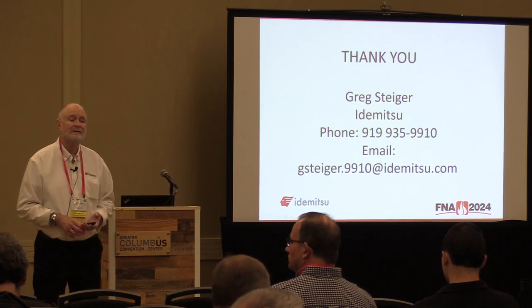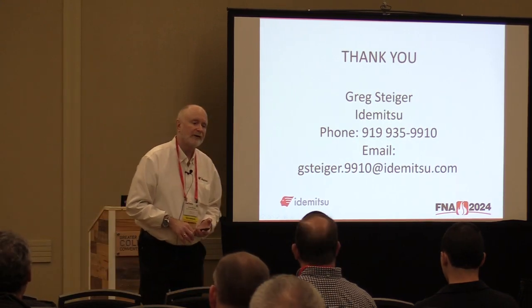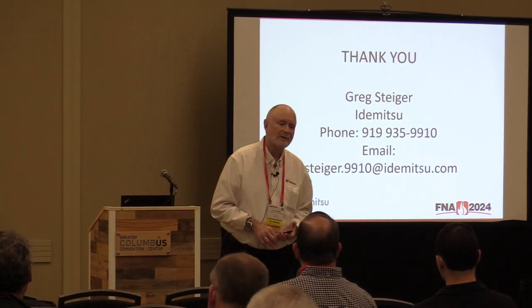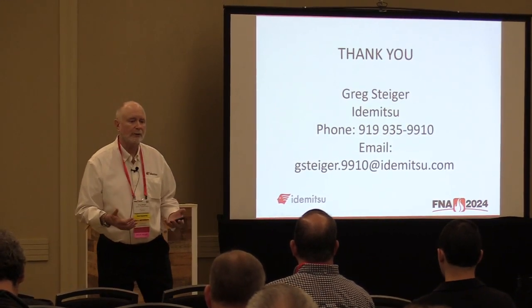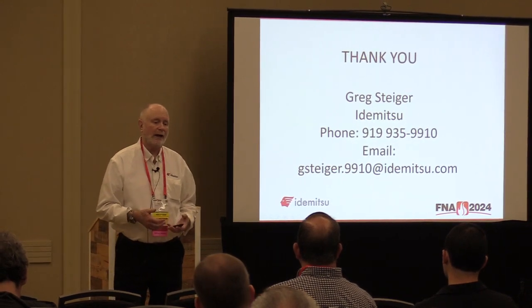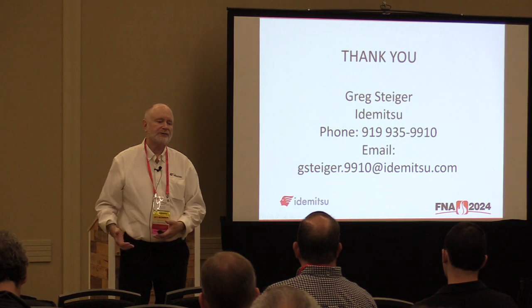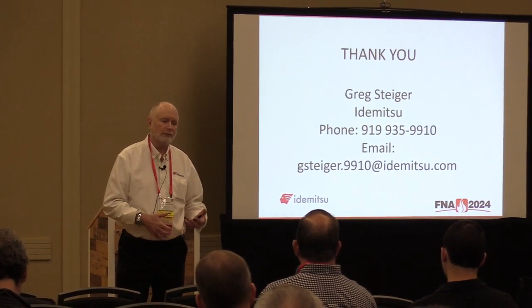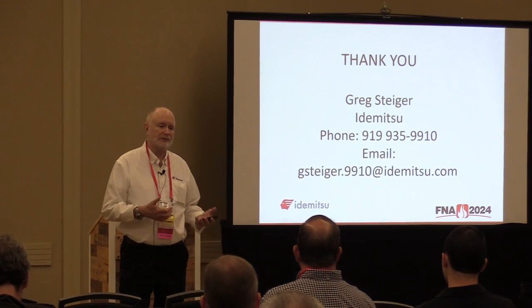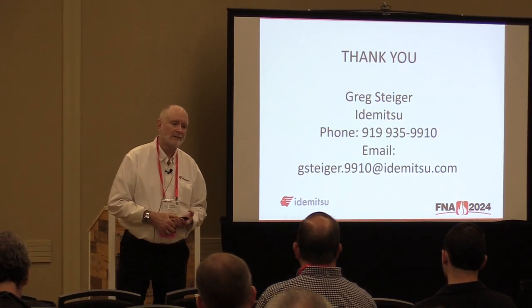What's the measure of oxidation of the quench? Is that the total acid number? It is. The total acid number titrates an organic acid in the oil, and it's what you can measure before oxidation starts. So as your total acid number increases, you know if left unchecked, your sludge is going to increase. Can that be reversed with filtering?